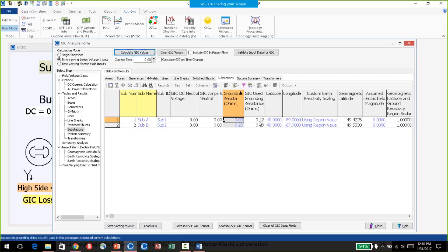The default is going to be between, I think, 0.1 ohms and 2 ohms, based on the size, the number of buses, and the highest nominal kV, which is not really a good guesstimator for grounding resistance. But we put something in there just for the benefit, so that if you don't have information, you can take a case and just start doing analysis.